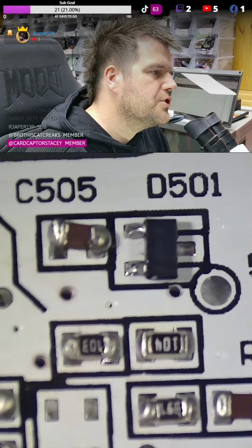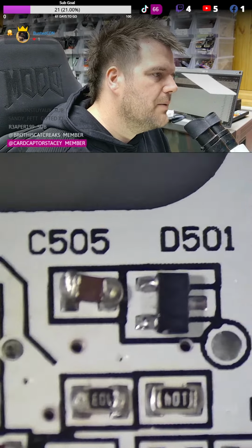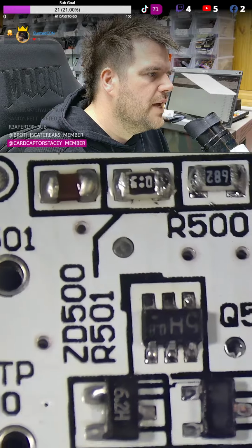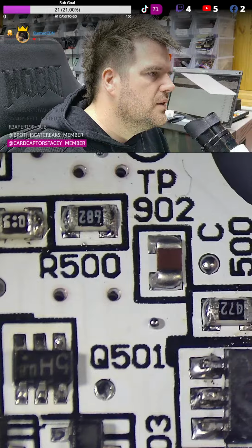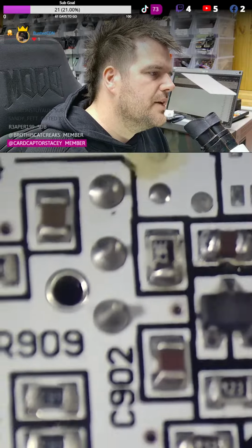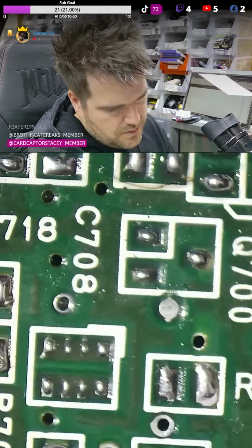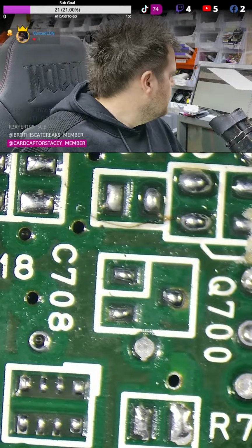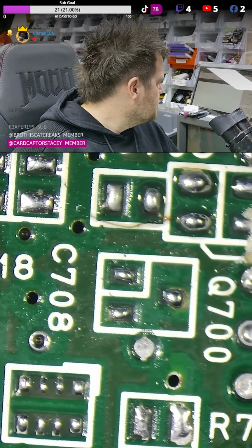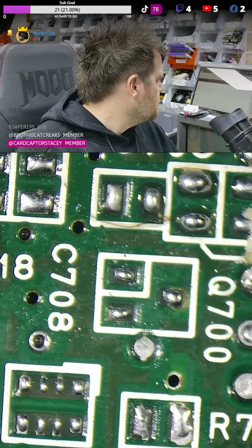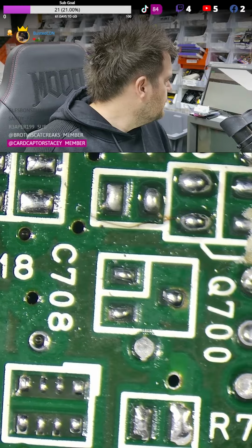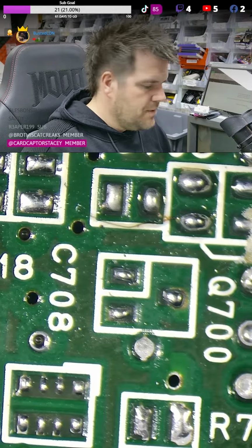So we had 5H. I bet we haven't got 5R, have we? And the 5H is on a transistor as well. So I'm just going to guess that the 5 is a designator for the type, which would mean that Q501, if we look at what that is, let me actually sort this spreadsheet now, but I'll sort it in a moment when it's filled. Q501 is a dual NPN transistor.